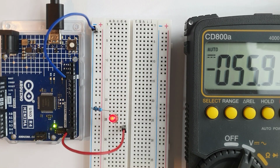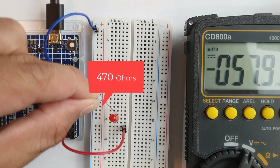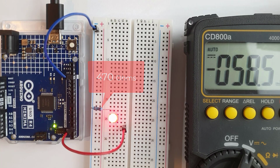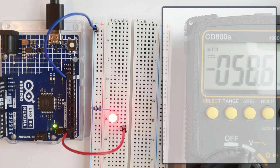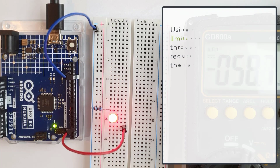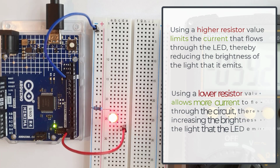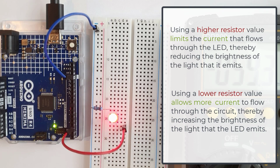And if I change this resistor one more time with a much smaller value, the LED's brightness is way brighter. It means that more current is flowing. So, what can we conclude? Using a higher resistor value limits the current that flows through the LED, thereby reducing the brightness of the light that it emits. However, using a lower resistor value allows more current to flow through the circuit, thereby increasing the brightness of the light the LED emits.